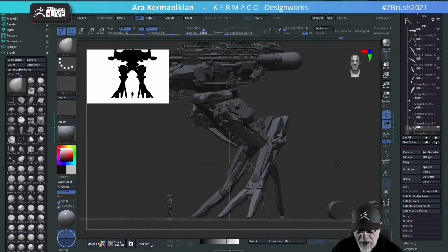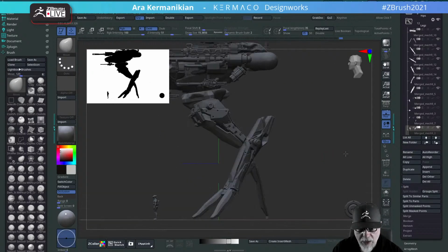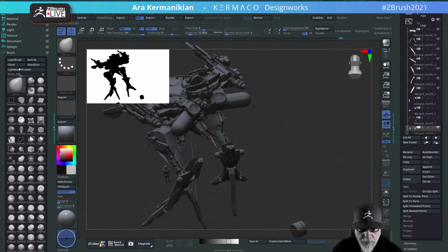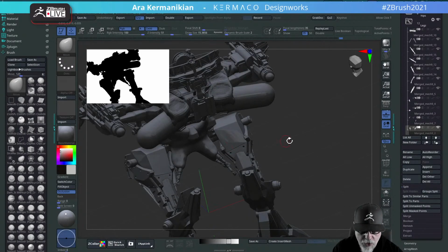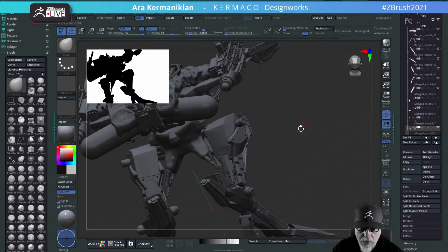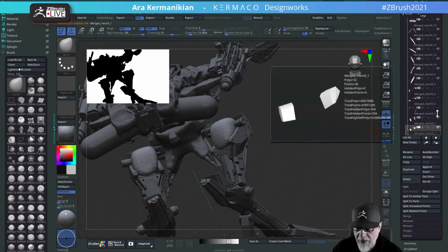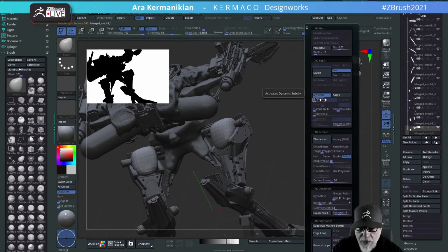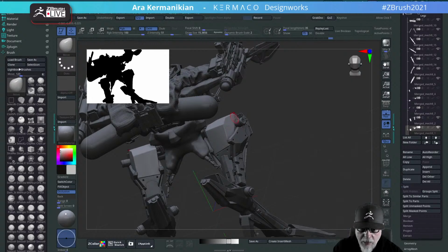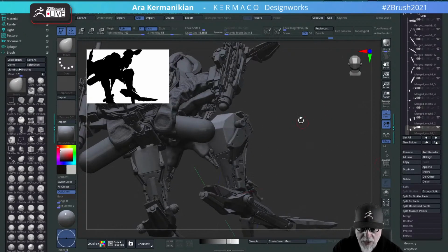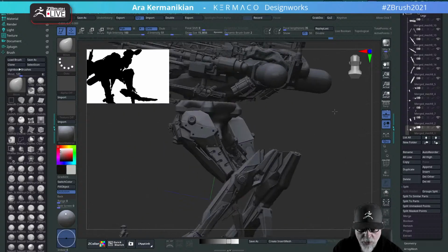All right, so again, just working on this piece right here, and that's looking a little bit better. And the back looks pretty good. You can see that really simple geometry looks like it belongs there. So all I need to do is go to Dynamic Subdiv for that. Oops, wrong piece. This one. Go to Dynamic Subdiv on it, and of course that's not what I want. So let's give it a Q grid of maybe 1 or 2, and then choose a coverage like that, and that piece now has a smoother shape to it, and of course I can always go in and add more to it later.